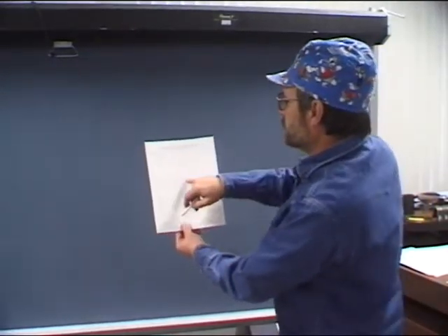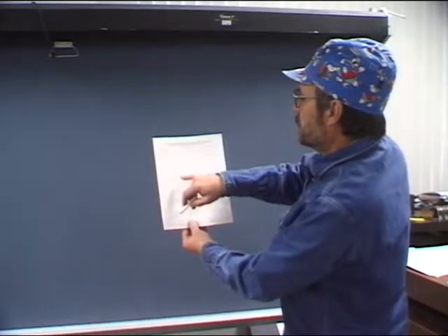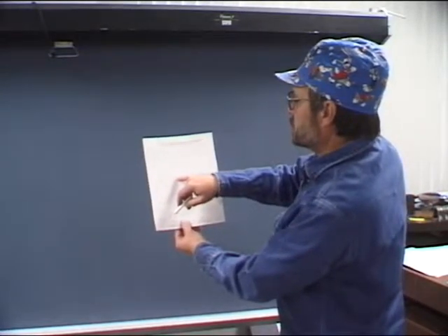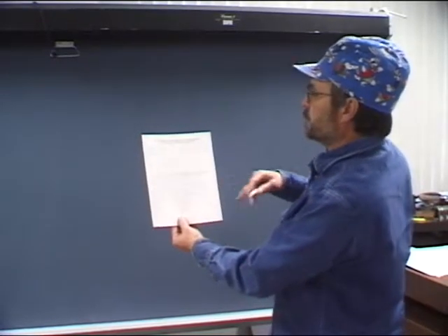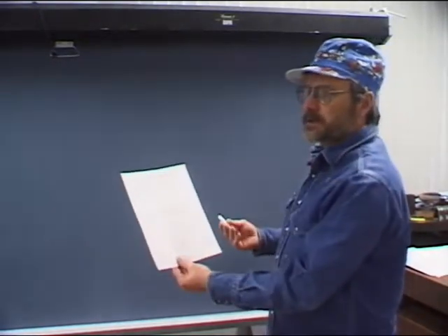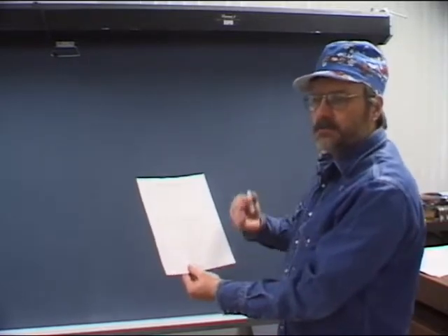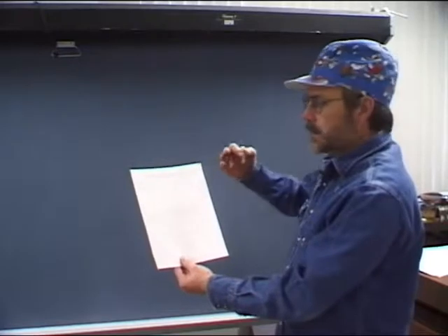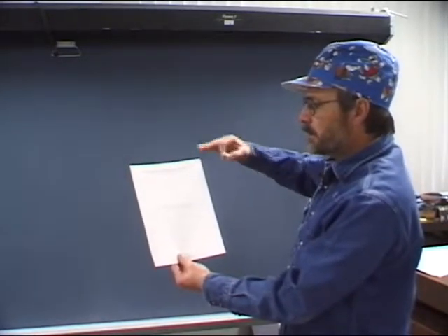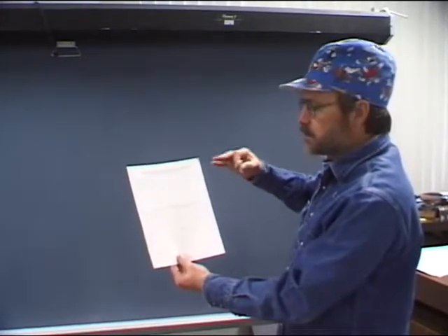So it says here, groove design of test coupon. And it says, for combination qualifications, the deposited weld metal thickness shall be recorded for each filler metal or process used. So if we're going to use two different processes, and it's very common to use TIG for a root and then switch to shielded metal arc for fill and cap, then we would have to record whatever metal thickness or deposited weld metal we use for each one of those.